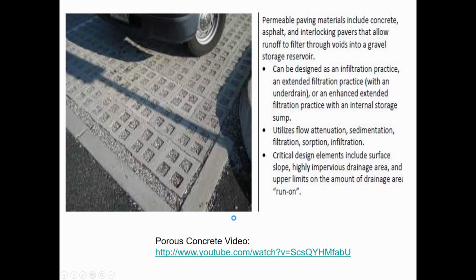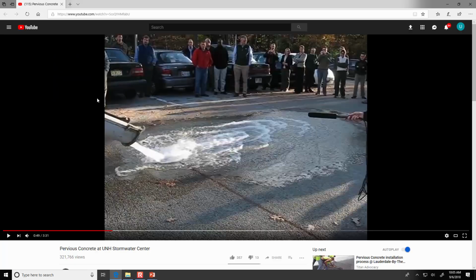And speaking of concrete, let's see if this YouTube video is still up. It shows some porous concrete. Because if you think about it, if the subgrade beneath the concrete isn't well drained, if there's water backing up and it freezes, it's just going to break that apart, no problem. And so I think the key to good porous concrete is to have some slope to it and to have big pieces of gravel, like a thick gravel layer underneath, so that the water can really move through and get out before it freezes.